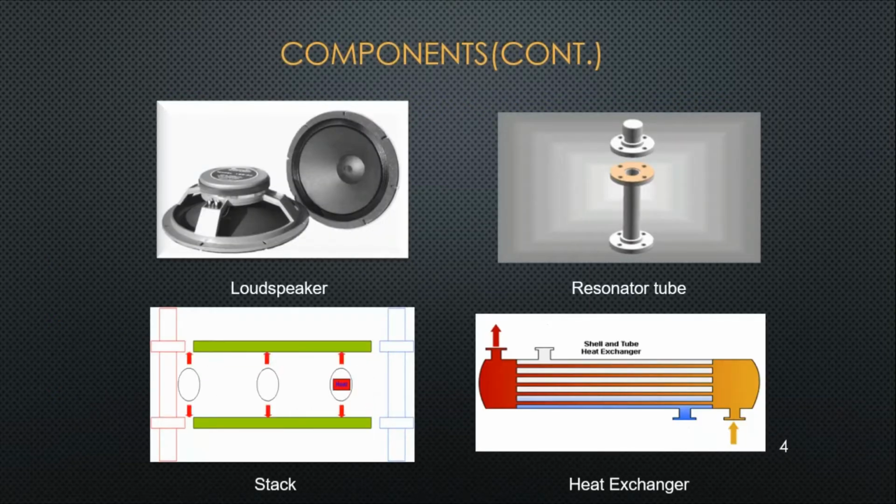So these are the components that I used in my project for the formation of the standing wave type thermoacoustic refrigerator. There was a loudspeaker as a source of sound that was attached to one end of the resonator tube, while the other end of the resonator tube was closed. In the case of the quarter wavelength thermoacoustic refrigerator, the other end will act as an open end. We will arrange it in such a way, but in my case it was a closed end.